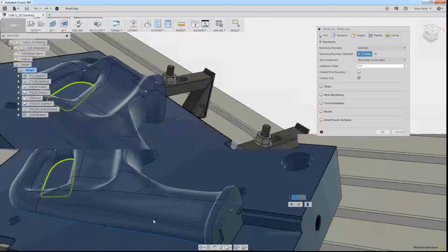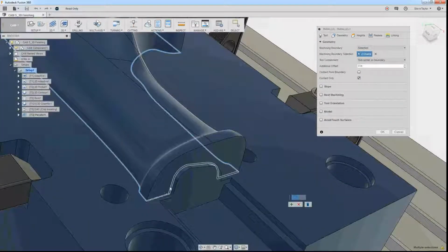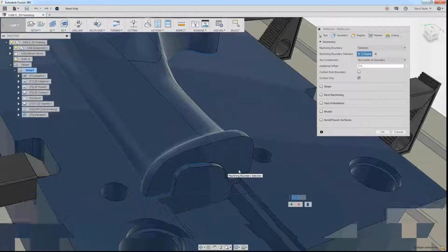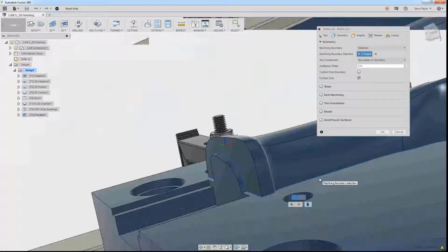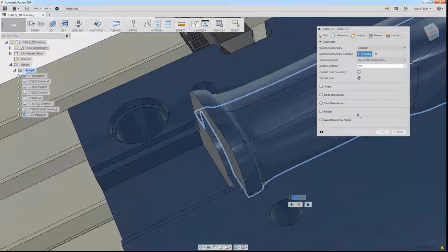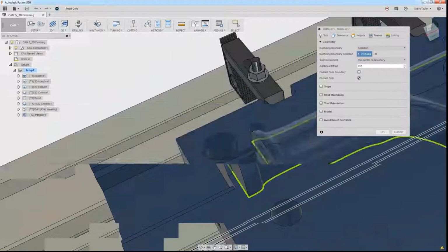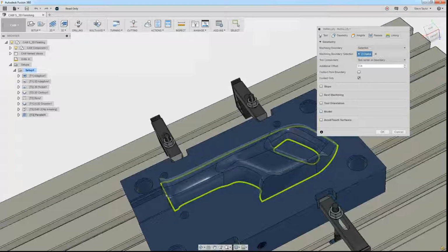And then we need to come into this bit here. I need to select that, and there. So we've actually now got all of the sections around it. If I click plus, that will now add the outer boundary. So we've got the inside of the handle and we've got the outside.